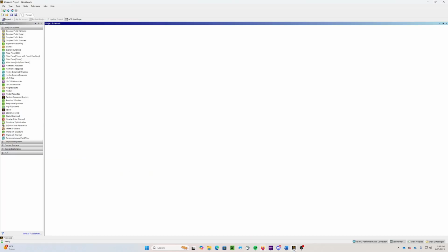So you first start off in Ansys Workbench. You drag and drop Ansys Fluent into the workspace workbench. The first thing you're going to do is set up your geometry. For this one, open new design modeler geometry.